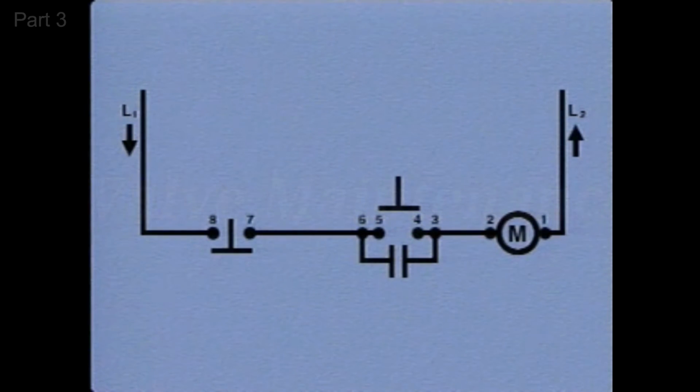We'll use a simplified schematic of a controller's control circuit to see how you can troubleshoot an energized controller that has a malfunctioning stop button. This simplified diagram represents the controller's control circuit. The malfunctioning stop button is represented in the open position. The electrical connection points shown on the diagram are numbered from 1 through 8 for ease of reference. In this example, the only identifiable symptom of the controller malfunction is that the motor will not start.